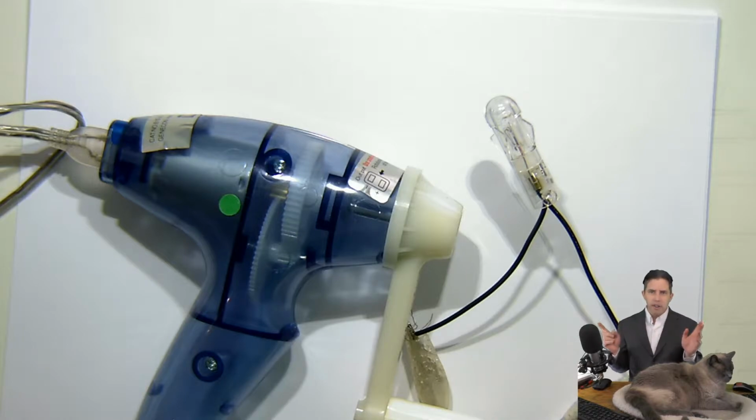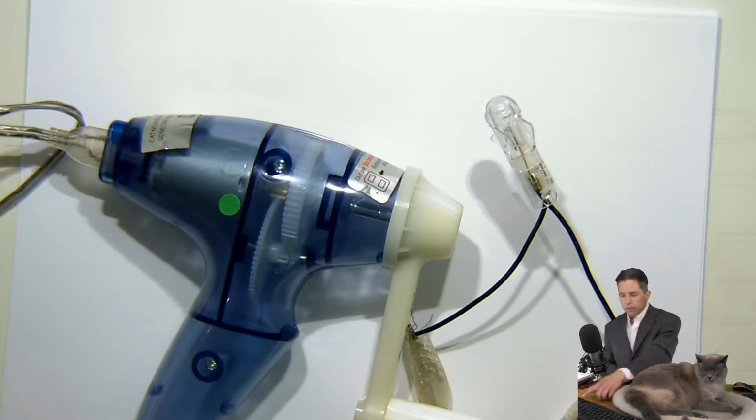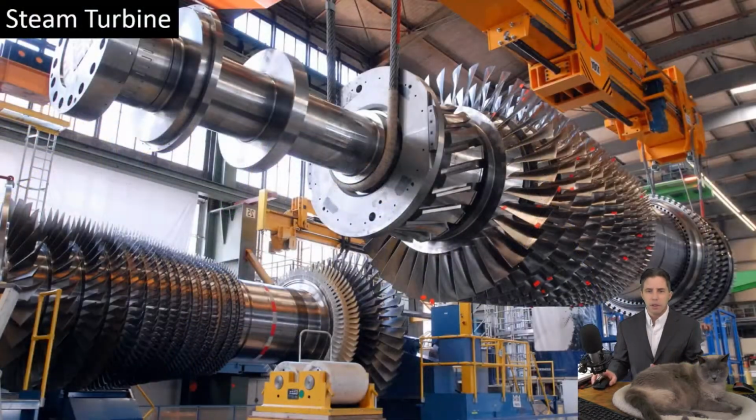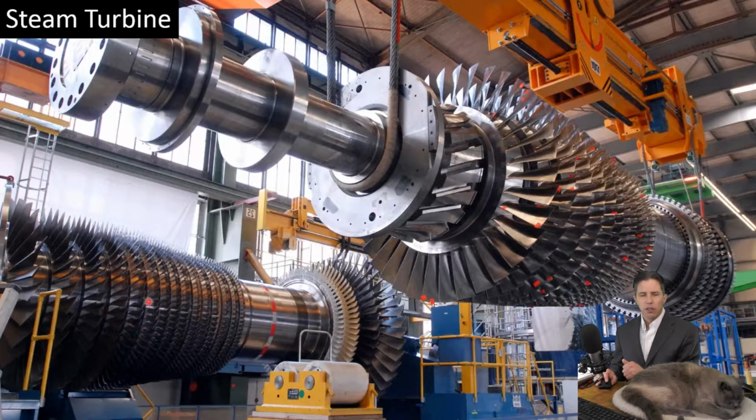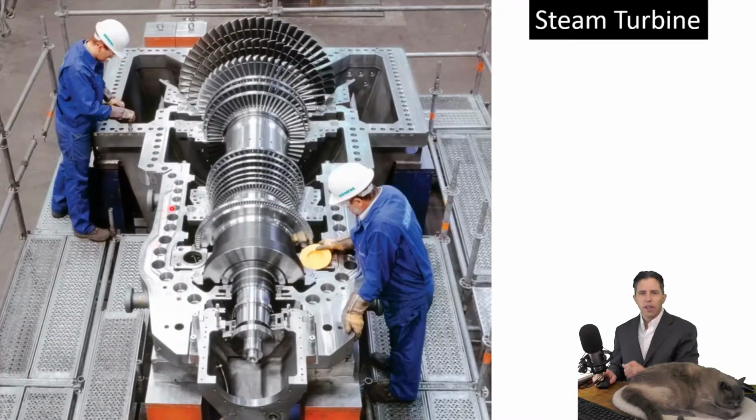So the wires are the conductor, a physical magnet or maybe a coil of wire is the magnetic field, but you need something to move it. And the thing that moves it is usually something called a steam turbine. A steam turbine looks like a giant fan, and these steam turbines sit inside a housing, and steam comes in these holes and pushes against the blades of this turbine, and this whole thing spins around and around and around, and on the other end it's going to connect to something that's producing a magnetic field that will then spin in the same way that I just spun that little one.